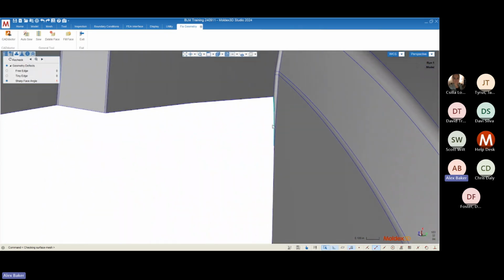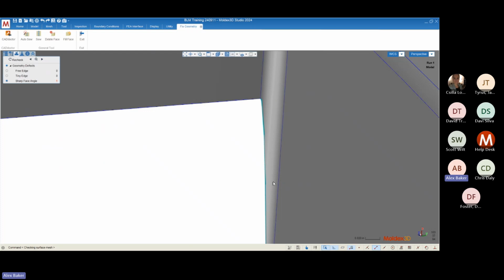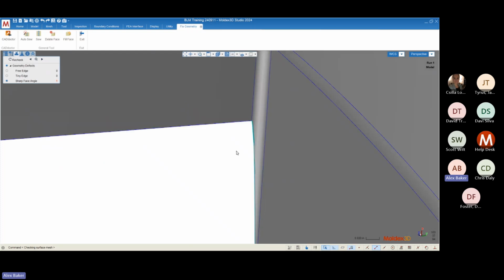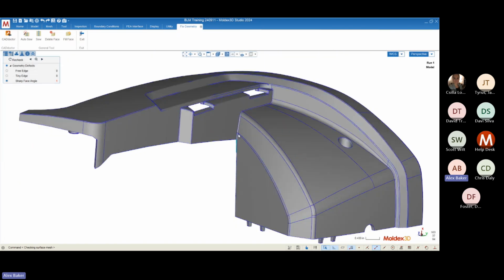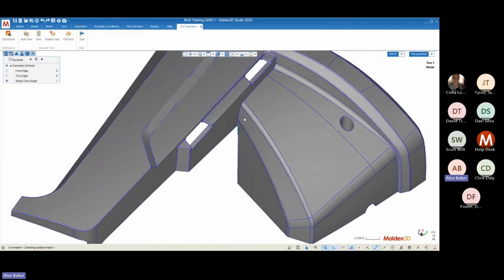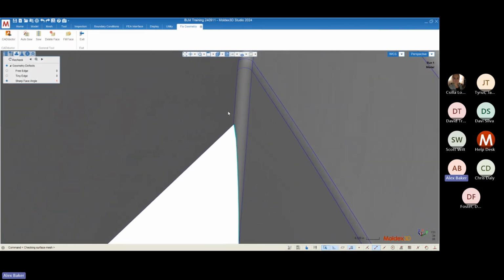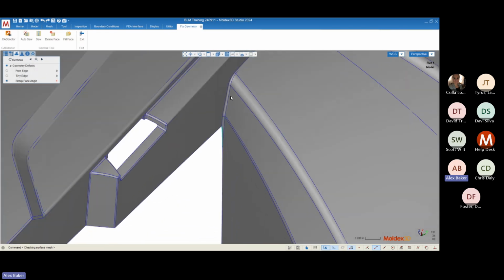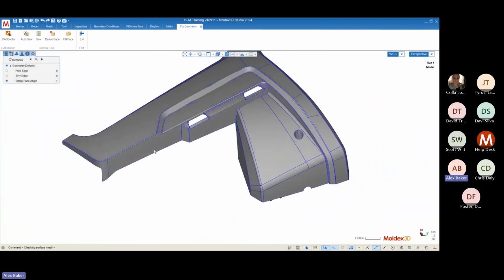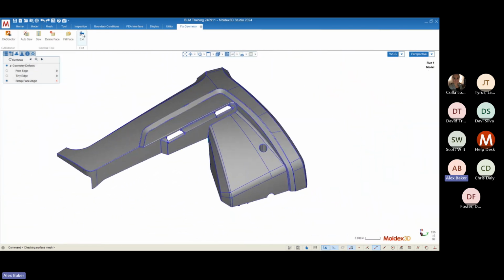which sometimes is an issue because if there isn't enough volume here, we can't really get the 3D solid mesh elements to completely fill this gap. And we might need to open that angle up a little bit, which we can do manually if it's ever a problem. Most of the time, the mesher is able to. It's not a showstopper at all.